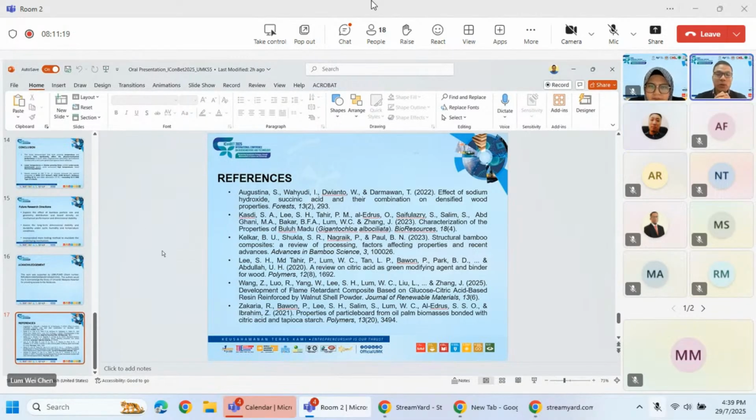Thank you, Dr. Boon, for your questions. In order to answer your first question, the moisture content is a very important parameter when we produce our particle board. For citric acid particle board, the particle moisture content is dried to 3% and below. The maximum is 5%.